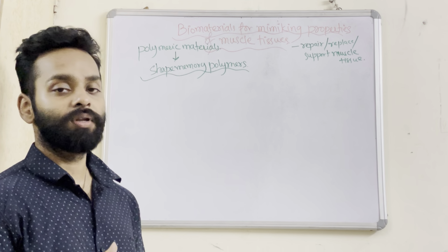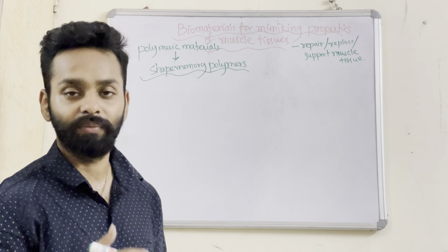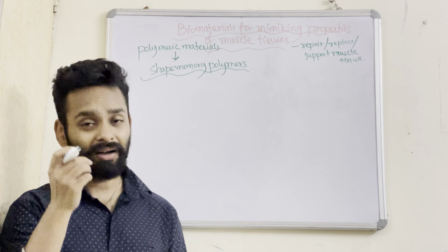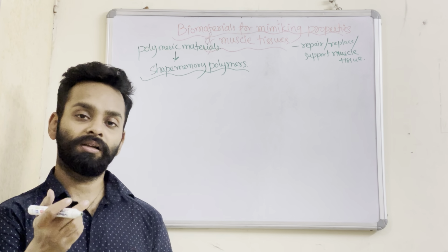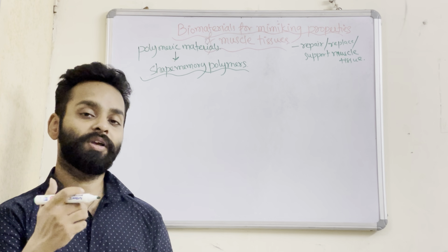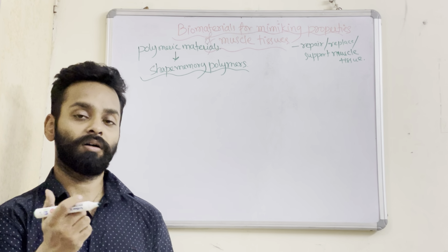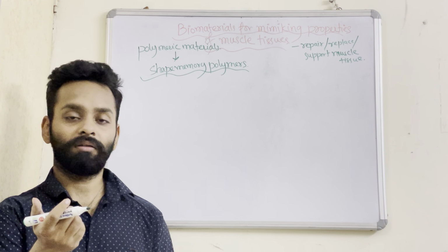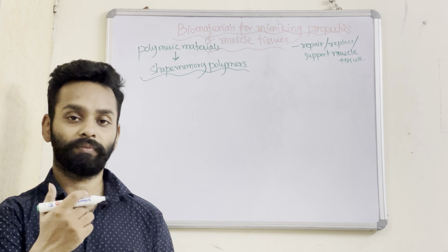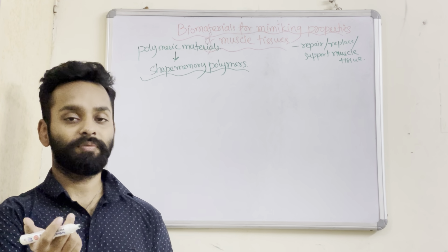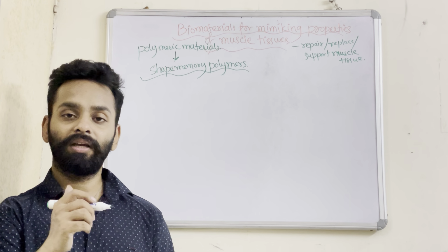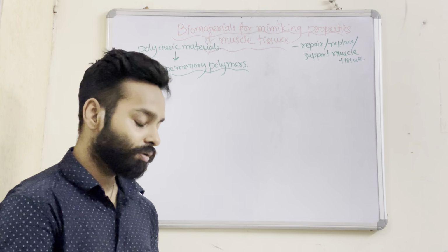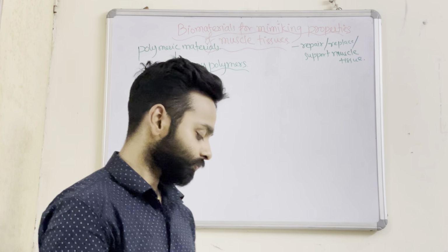So such polymers are known as polymers which exhibit this shape memory effect, and the various types of stimuli which can be applied can be changes in external temperature, pH, or some chemically added agents which can be used to stimulate this type of relaxation. Even electrical stimuli can be used, or even light stimuli. So light dependent polymers. There are many types of polymeric systems which can be fabricated to display this shape memory effect. So these are the different types of stimuli which can be used.